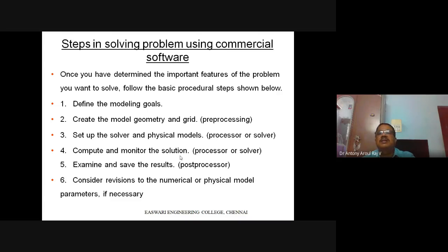So this is the basics, and don't think that these basics are only for our discussion today. This is applicable for general CFD, and also for finite element analysis, where you do the same thing. For a structural problem, you first draw it, then mesh it, give the boundary conditions, solve it, and go for post processing. In post processing you can get the plots, like contour plots and vector plots. Sometimes if you are doing a transient problem, it can be a time dependent contour plot. Time dependent information you can obtain by a transient analysis. So that is the structure of the equations.